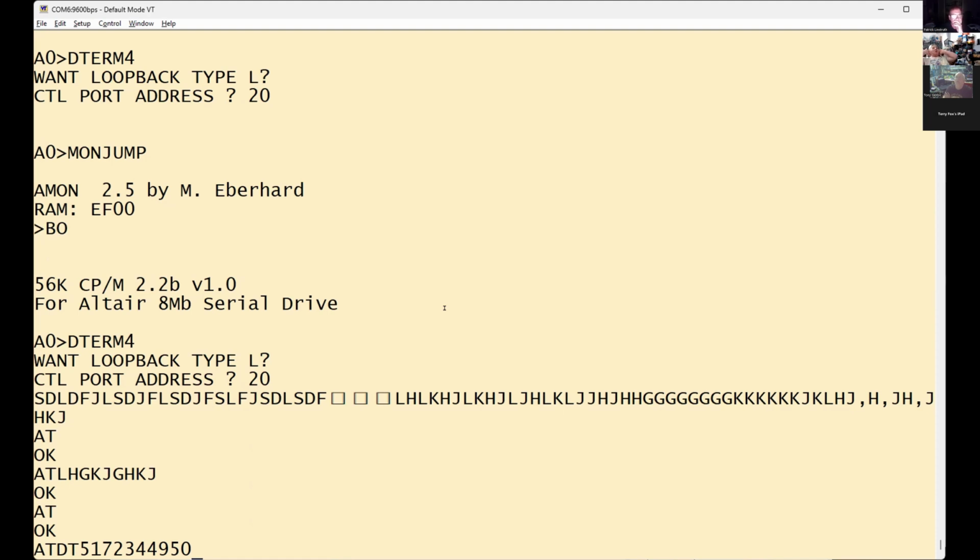And those are 20s. So it's at the front, colon 2. So the next 32, or is it 64? Next 64 alpha characters are the hex. So you're getting 32 hex characters over. And then the last 2 characters is a checksum. That's an Intel hex format. So that's not address. Your address doesn't start until 4 characters before the data.